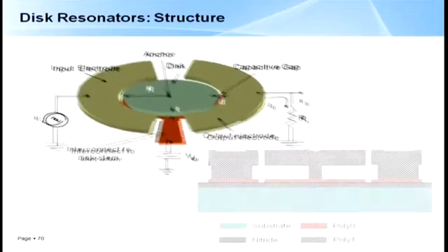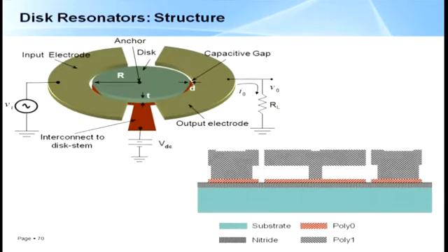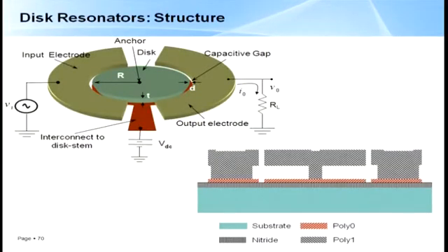Next, quickly moving to the next important thing: this is a varactor, then can you make a filter, or I say the clock? Why not make the clock inside the chip without going to the crystals? Now the only part remaining in the transceivers is the clock, that is the crystal, and the crystal is bigger in size. So, can you make a clock using some kind of a micro machine structure? That can be done by this kind of resonators.